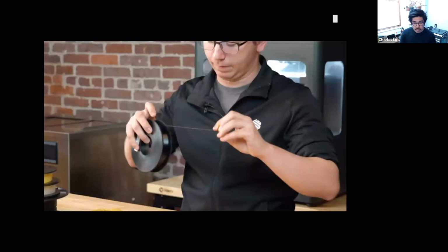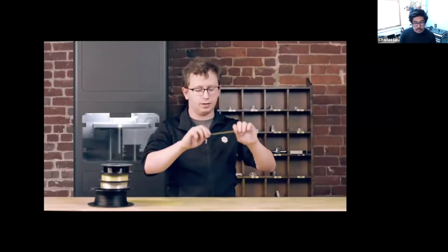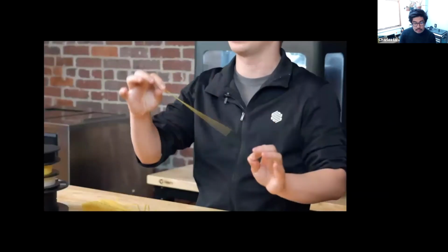It all starts with a strand of fiber like this one. Fibers like carbon fiber are so valuable in engineering because of their strength to weight ratio, specifically when applied in tension. Alone, they sort of behave like raw spaghetti. You can easily break a piece of spaghetti by bending it, by compressing it, or by shearing it. But it takes a lot more force to break a strand of spaghetti in tension by pulling on it. And that's how fibers are most often used in composites.